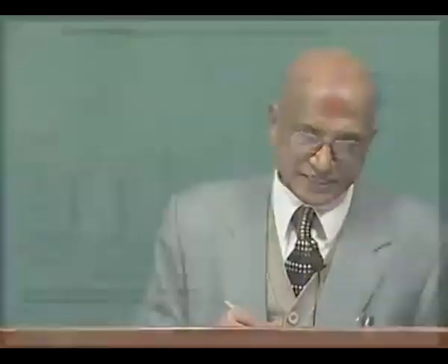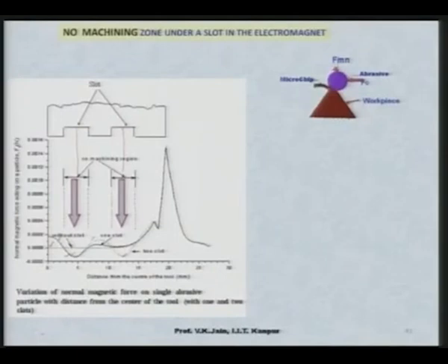And also we can see there is a curve showing 2 slots, and a curve for 1 slot. In the 2 slot case, the forces, both negative and positive, are slightly higher than in the case of 1 slot. So we also conclude that there is some advantage, but not a substantial difference between 1 slot and 2 slots. At the most you can go for 2 slots. If you increase to 3 slots or 4 slots, you do not get any substantial advantage.